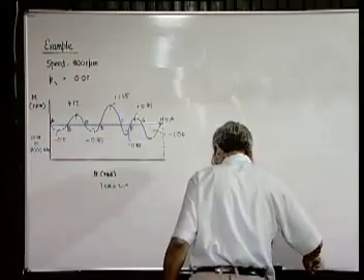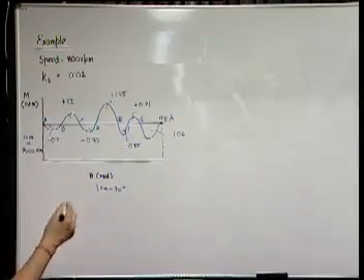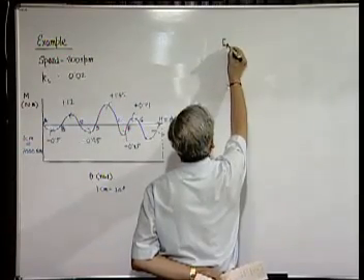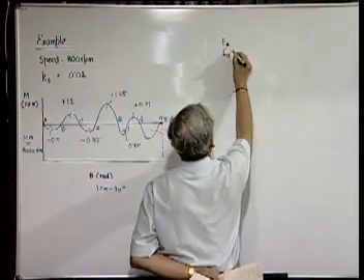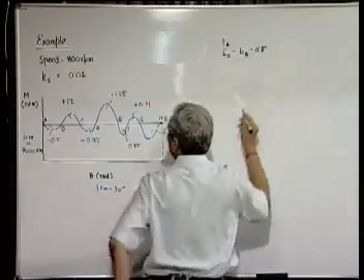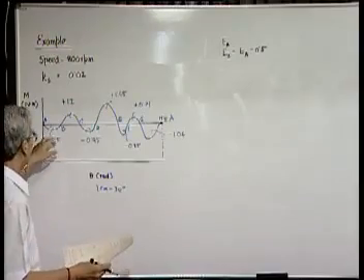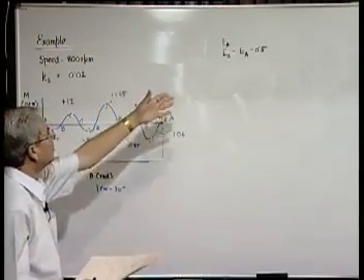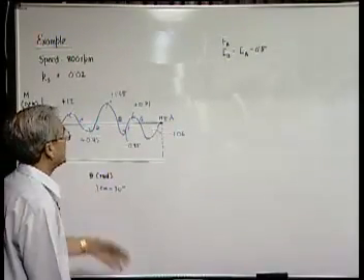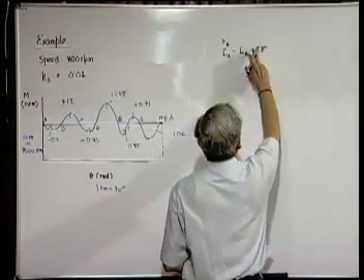Next, let us find out what is the maximum kinetic energy and minimum kinetic energy, as we have been doing. How do we do? We start with A, say energy at A point is EA, energy at point B is EA minus 0.5. We need not convert this centimeter square into energy now. We can do it at the final stage, because if we just keep everything in terms of the area, we will be able to identify the maximum and minimum, and then we will convert to the real energy units. So the energy at this location is EA minus the equivalent of energy, which is this.